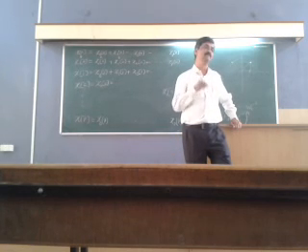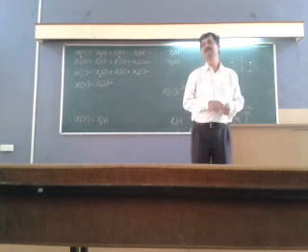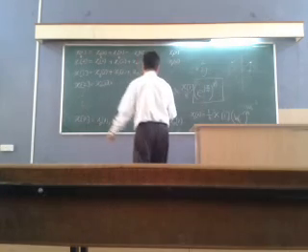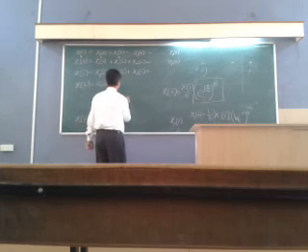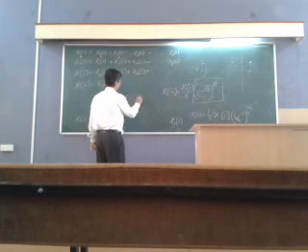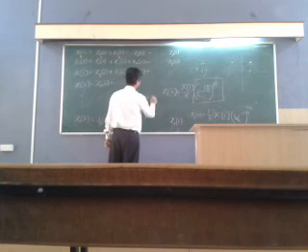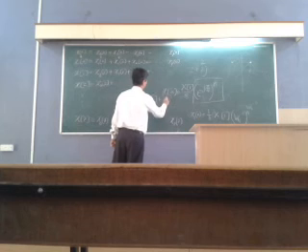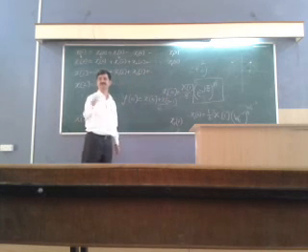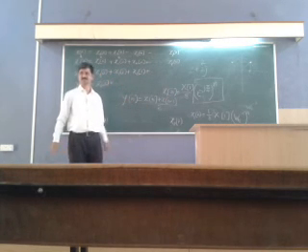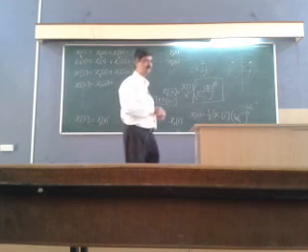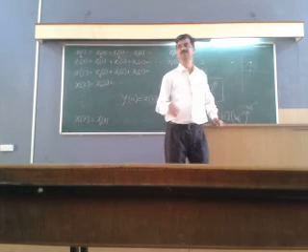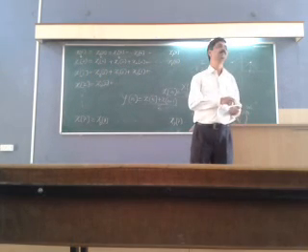So what is the simplest discrete time system which we also considered? That was yn is equal to xn plus xn minus 1 upon 2. That is the average of current and previous sample. It is a simple system. yn is xn plus xn minus 1 upon 2.